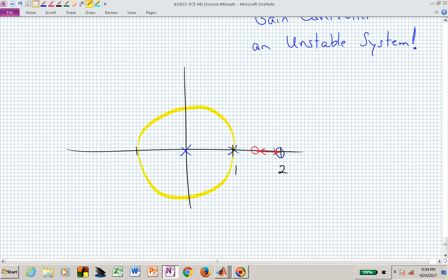So we actually have to introduce, in concert with that zero factor, a pole. And now with one pole and one zero factor, we do have a causal controller. What we now have is two branches of our root locus, a segment of the real line that belongs to the root locus, and this segment of the real line that also belongs to our root locus.